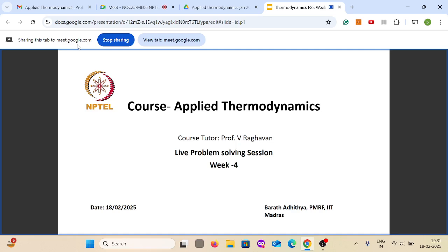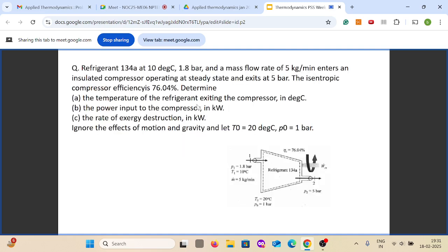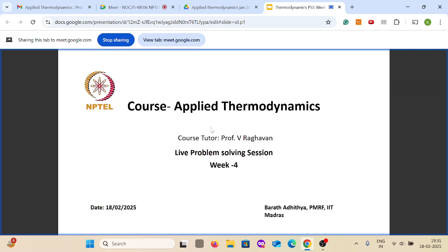This exergy balance is just a combination of the first law and the second law. So do an energy balance and then an entropy balance and combine them together, and you get an exergy balance. That's what we did, even in an unsteady process. With that we can easily estimate the exergy destroyed, and we have covered the exergy portion.